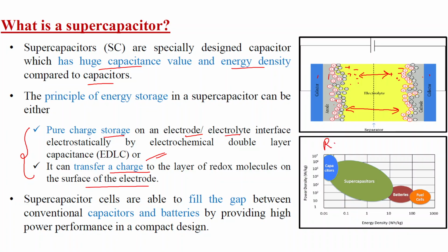We discussed the importance of solar energy and the different generations used in solar energy. First generation solar cells are wafer based, whereas second and third generation solar cells are film based. Perovskite solar cells are recent. They achieved efficiencies of 3.8% in 2009 to 23.3% in 2018. So within 9 years they have reached almost 20% extra. Solar thermal technology uses sunlight concentrated onto receiver tubes, in which the heat transfer fluid gets heated up, which is used in running the turbine.